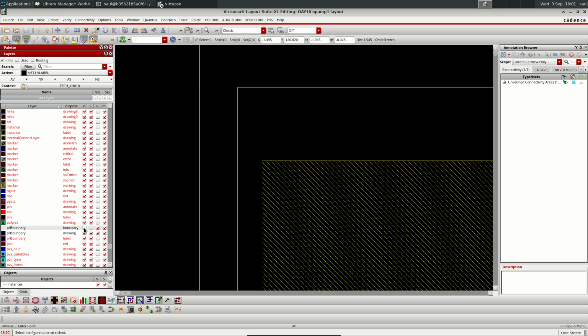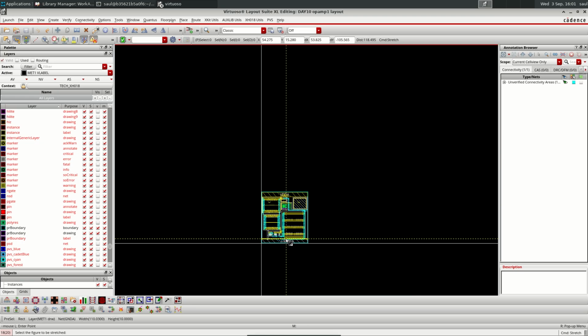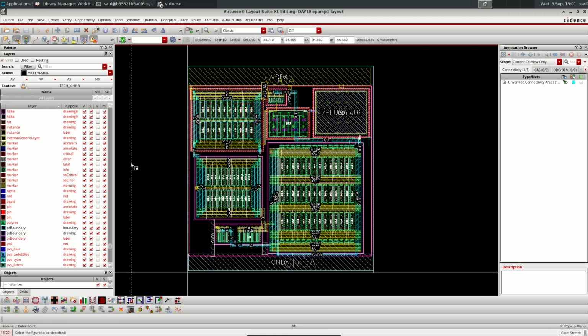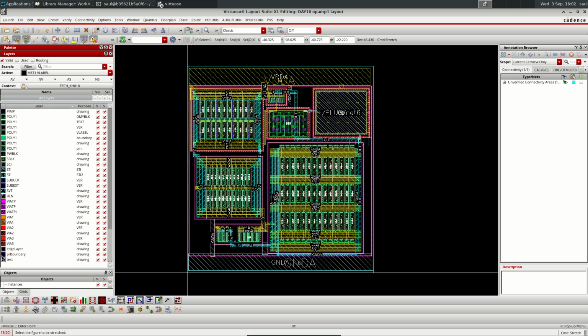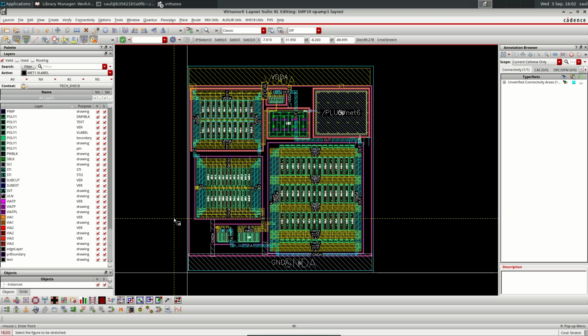Let's see, make it invisible, this one. There is another layer there, but we will see what it is. Maybe it is the DRC LVS that was putting something else on the top. It's important to not touch that one, so I will make it not selectable and not visible, the PR boundary. And okay, I press L again, and then I come back to only the visible layers that I need. Okay, so with that we are ready.